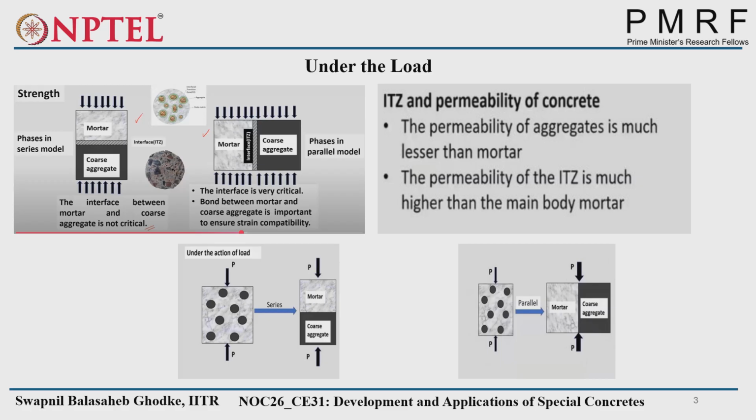That tries to fail easily. When it fails, there will be no strain compatibility. That's why it is a critical part. And why do ITZ and permeability have a direct relation? Because of the high amount of voids creation. Because of the high amount of water, some will evaporate and create voids. And suppose we have voids in the concrete.